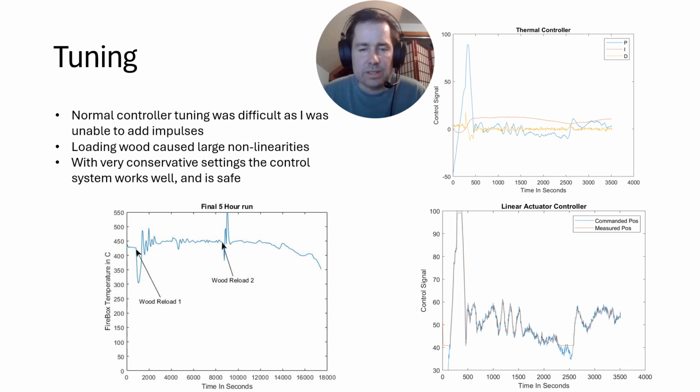With more days of testing and slowing the system down by a factor of 60, I was able to get the system under control. The proportional controller is now much less aggressive, and I allow the system to be overdamped at startup. During April, we had a 48-hour power outage in Estes Park, so this allowed me to run the system all day, tuning and updating the controller.